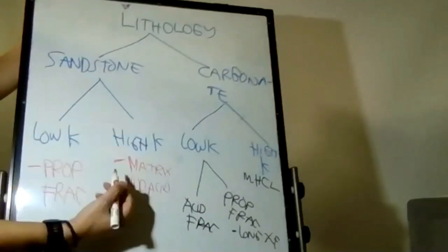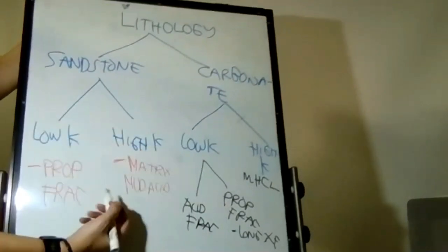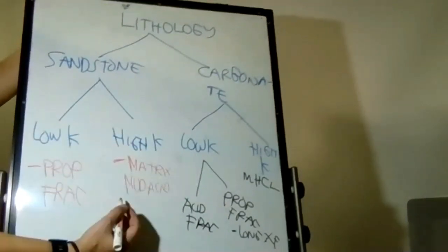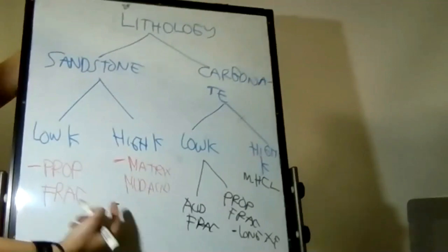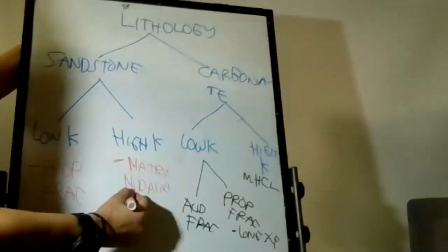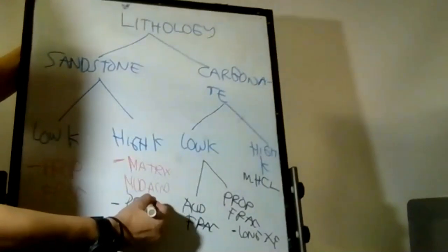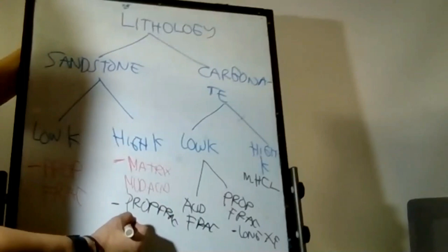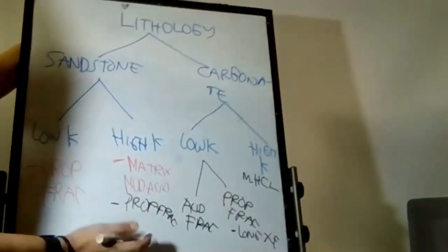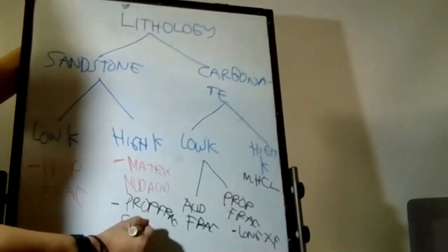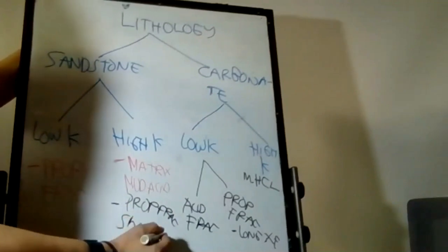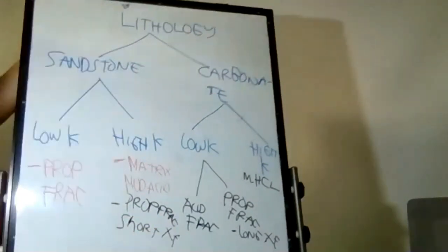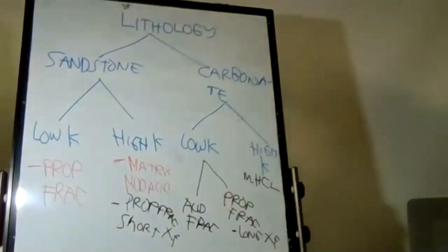On your sandstone here, if you deal with the high permeability, not only you can do matrix acidizing, but you can also do the proppant fracturing, prop frac, but short half length. Remember that TSO, short half length. Okay. All right, guys.